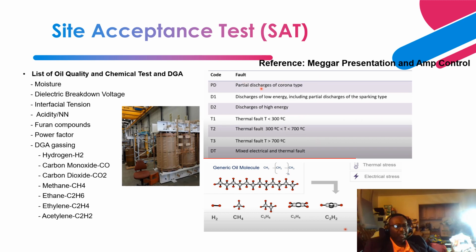An acceptable degree of polymerization is between 800 and 1200. Anything below that is unacceptable, so you put in intervention measures to plan for the transformer to be rewound, right? And if you measure furan compound that is giving you a degree of polymerization of 200, then that is a cause for concern for you to take the transformer out of service immediately.